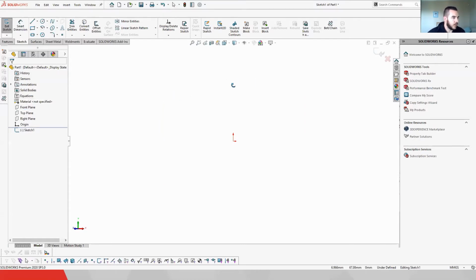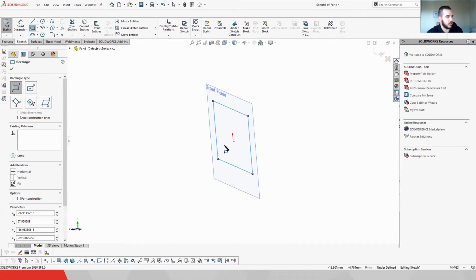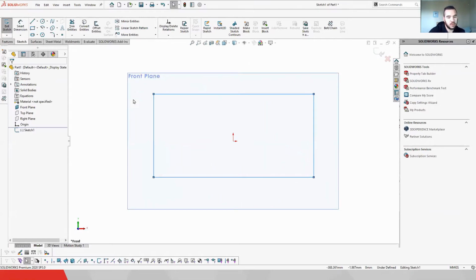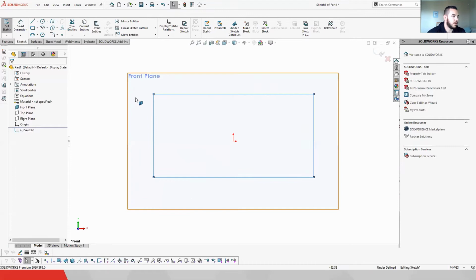The reason why I do that is if I want to draw like this, and I want to draw a square, it's quite difficult if this thing is not normal to know actually how the perspective is making it. So always Control 8 to normal to, or you can do Control 7 for isometric view. Just a few shortcut tips that I'm just showing you as well.